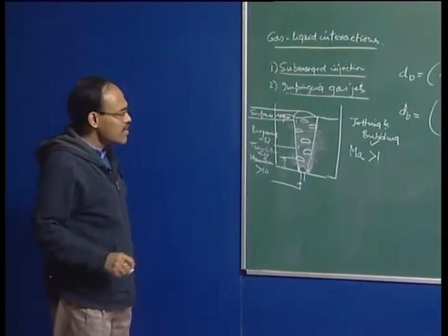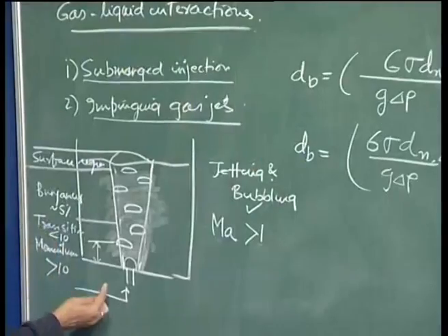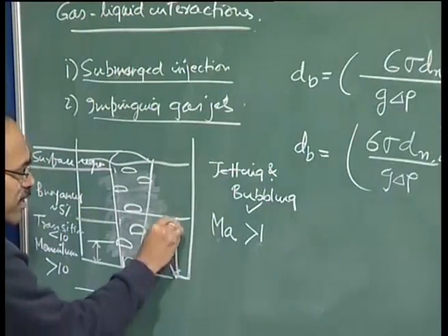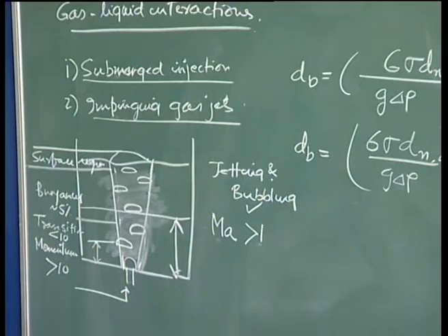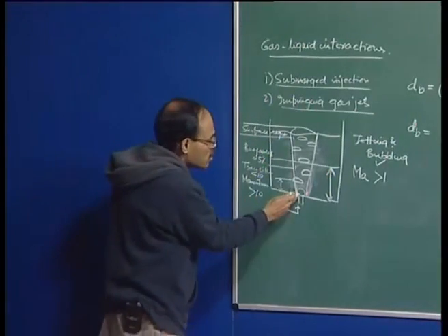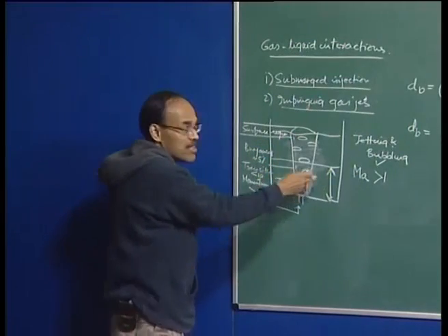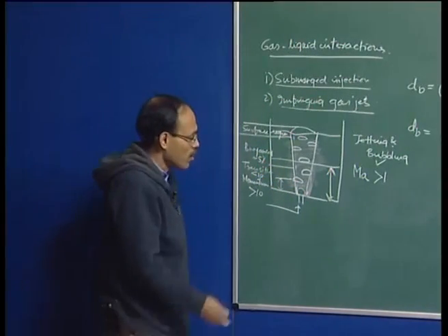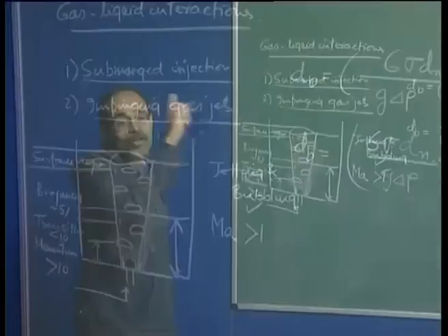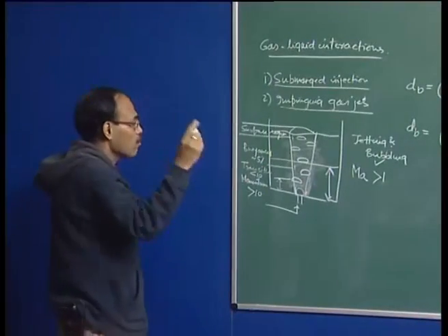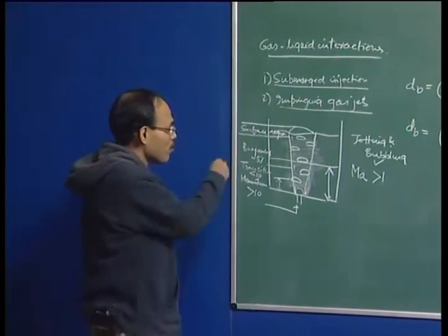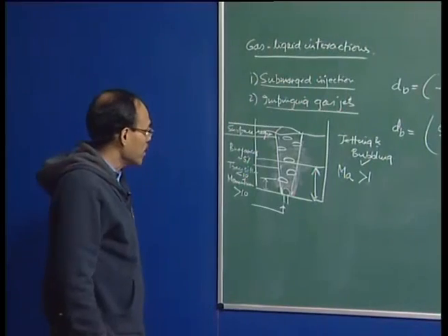One important characteristic comes when we are injecting a reacting flow and you have a small, shallow bath depth. Ladles and so on have bigger bath depth, but when you have shallow bath depth you have swirling motion. So even though this configuration looks like a two-dimensional or an axisymmetric configuration, with shallow bath depth and injection at high rate, you can introduce a lot of swirling or rotational flows in the system, which can aid in mixing in the process itself. And in OBM converters, this is very commonly encountered.